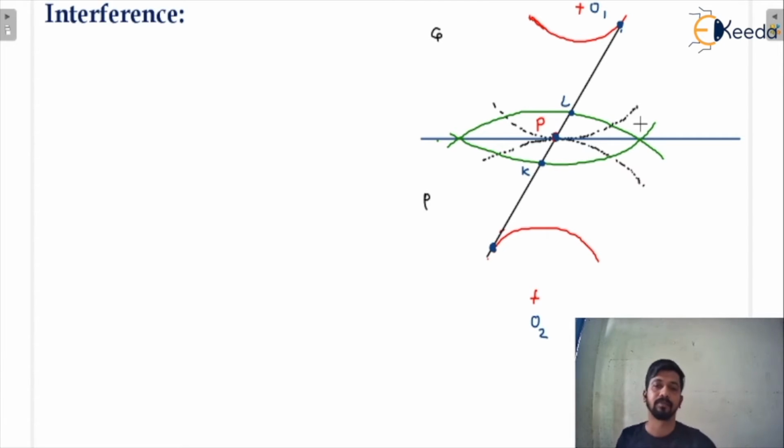Now, what does the law of gearing say? We have studied that the law of gearing is satisfied when the line of action passes through the pitch point, that is a fixed point, and it is tangent to both base circles, the base circle of the gear and the pinion. So this is basically the line. This is the law of gearing. The law of gearing must be satisfied for a body to be considered a gear. Are you getting my point?